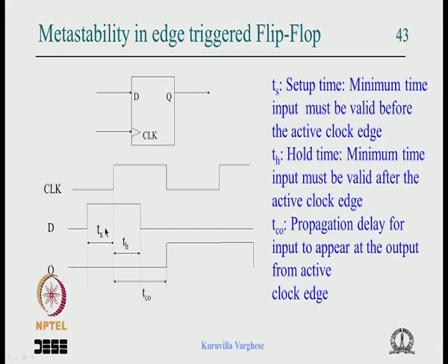But if the setup or hold time is not met, then we are not sure whether the 0 at the output may remain 0, or it might become 1. So we can't say, maybe it will change state or it may not change state. It is still an acceptable behavior, there is no harm, because earlier it was 0, and we are expecting it to go to 1. Since the data is changing in this window, the data is not set up properly.